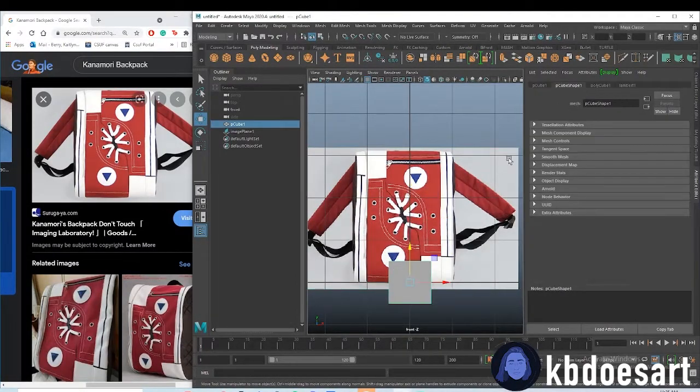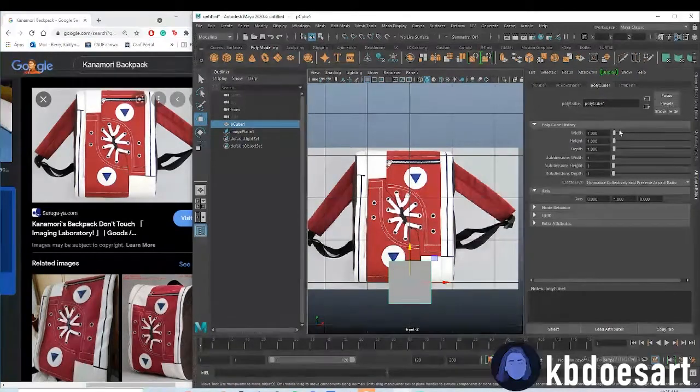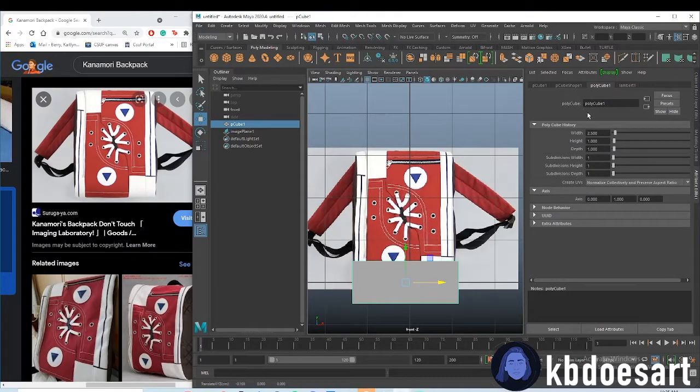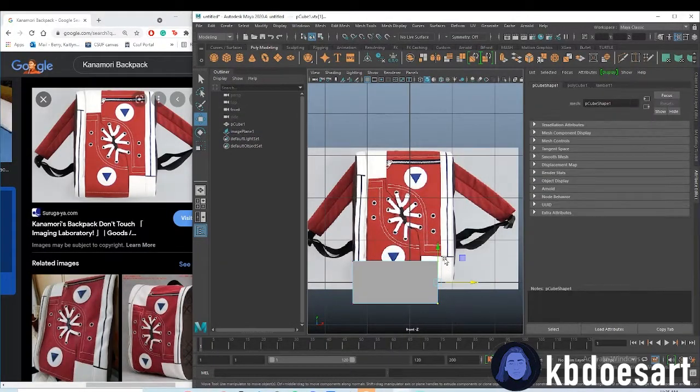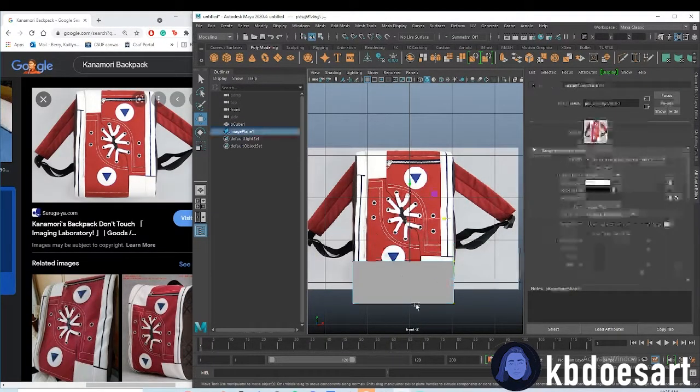Okay, so for our actual cube, let's change our dimensions a bit to better fit what that's going to be. Let's just aim for 2.5. Let's move it on over. Oh, it's actually a little too big. Let's do 2 then. Oh, close. So let's go into vertex mode, grab those vertices, and just push them on over.